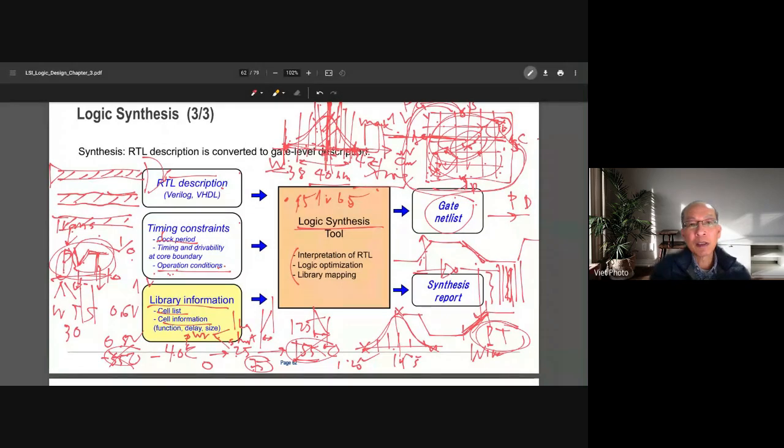Short circuit power. So it will show you this cell has how much leakage, and along with that you will have the short circuit power, which you have with the input slew and with the output load, right? Based on that, the tool can calculate the power that the cells consume. Then they can balance when they synthesize to meet the performance requirement. They will decide to use the cell with less power or more power, right?